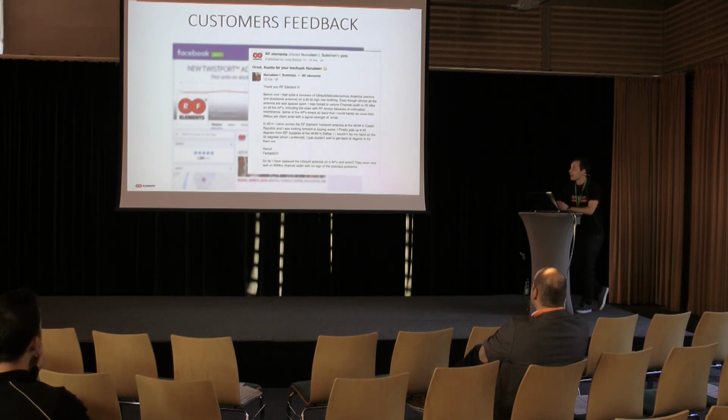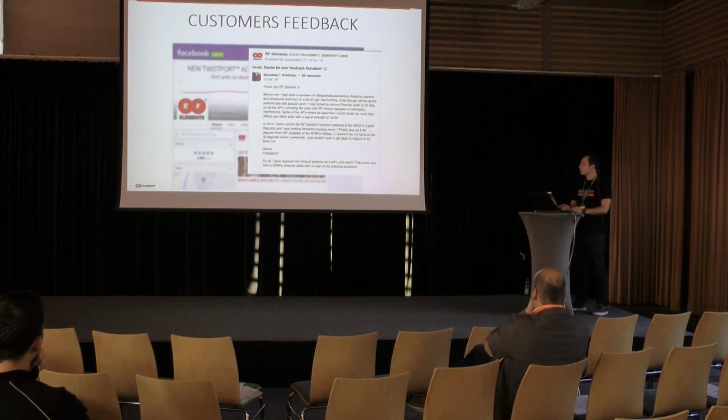This guy was not able to do 2 megs per client with a signal strength of -67 dBm. Then he started to use 60-degree symmetrical horns, and now he's even able to operate at an 80 megahertz channel.